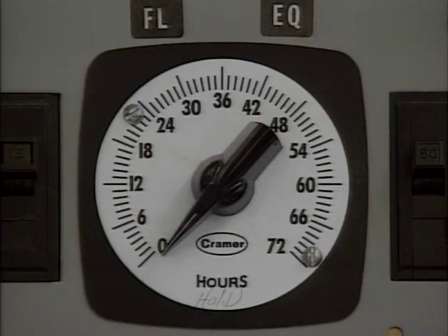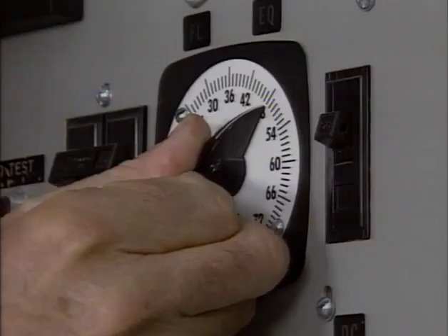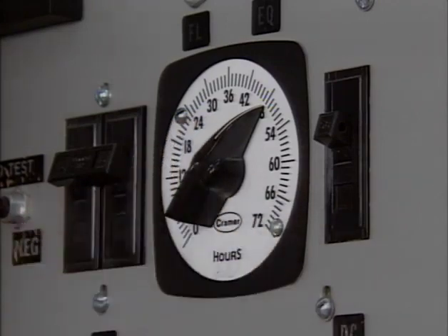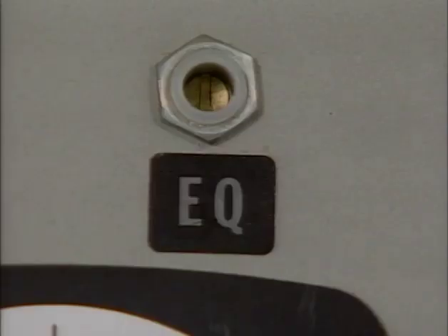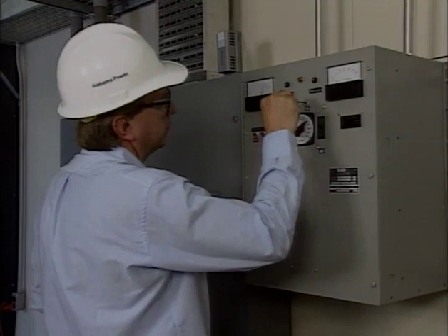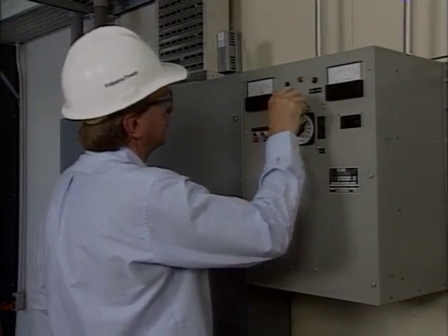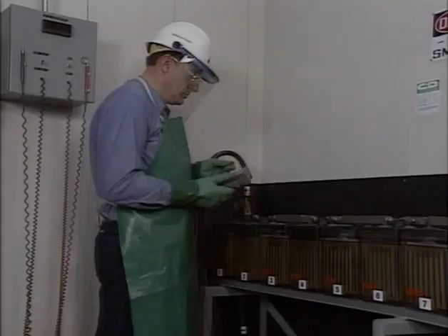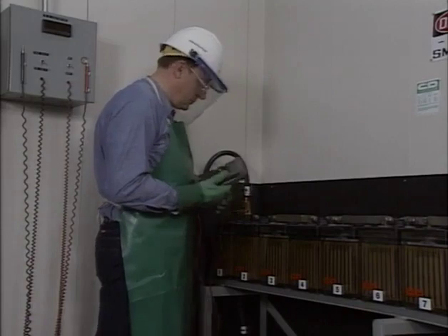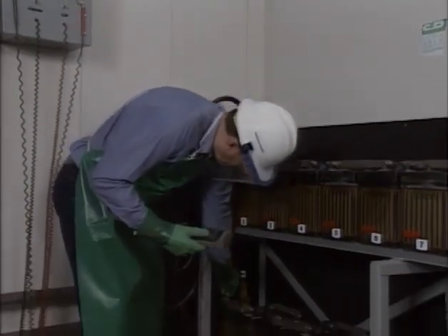To apply the equalizing charge to the battery, the float equalize switch or timer on the battery charger is set at the equalize position. The equalizing charge is applied continuously for 35 to 70 hours or longer. If the charger equalizing output voltage is the same as the freshening output voltage, the equalizing potentiometer will not need to be changed. If the equalizing and freshening output voltages are not the same, the equalizing pot is adjusted to provide the required equalizing output voltage. As usual, the charger voltage output is verified across the terminals of the battery.